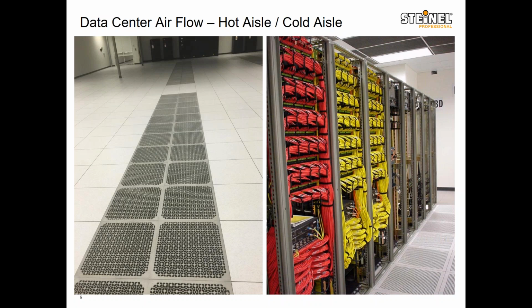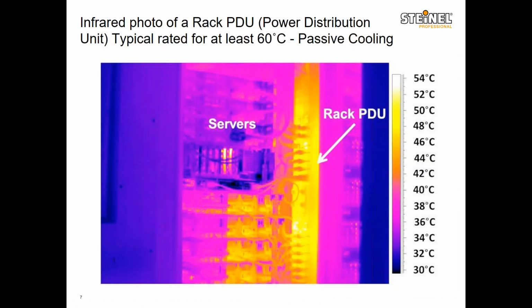On the right-hand side, you'll see after they place the server racks. They line the server racks up directly on the edge of where the air ducts come up through the floor. You can't see it all here, but there's a piece of plexiglass that runs across the top that makes the air seal. And you can see how the air would flow through those server racks.